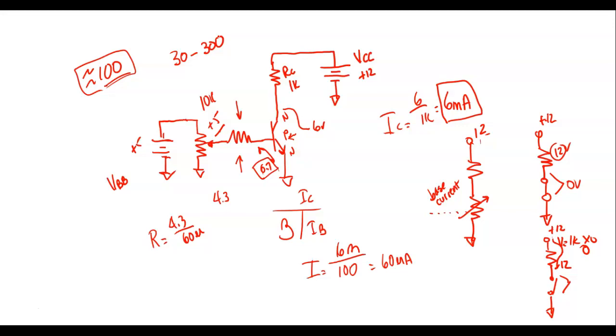So what size resistor would we use right there? Yeah, 71.6. We didn't have a 71.6K, so I put in a blue, black, red. I can't tell that color, guys. Blue, black, red. Oh, that's not even an orange. No wonder I was having problems. Oh, no, I changed it out.